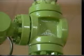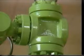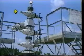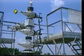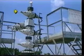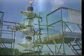Above the actuator is the production T, which directs flow from a vertical to a horizontal path. A gate valve is often placed above the production T to facilitate the easy installation or removal of a lubricator. This gate valve is usually called a crown or working valve. On top of this crown valve, or if no crown valve is used on top of the production T, a tree cap is installed. The tree cap provides quick access to the tubing bore for wire line or other operations.